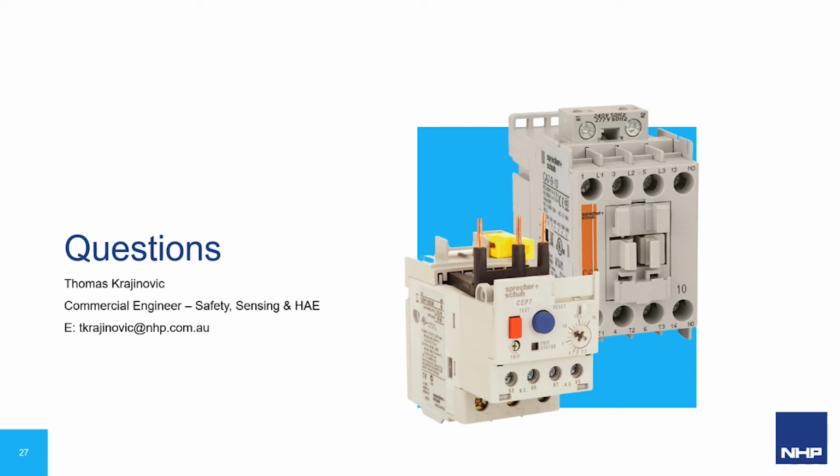So with all cases except for EXE protected motors, VSDs can be used provided you're directly monitoring the temperature of the motor. So if you have a motor with thermistors that's not EXE, then you can use any of our drives technically.